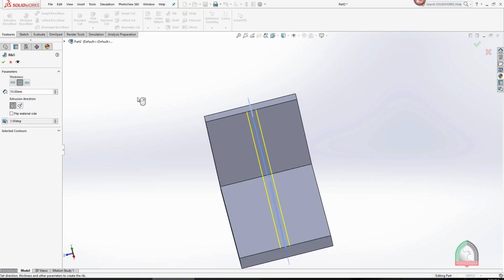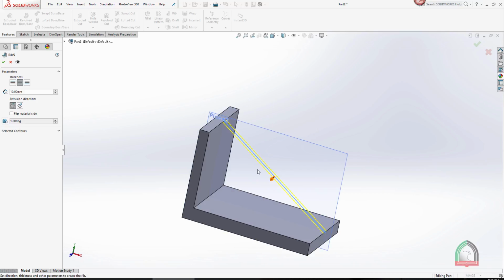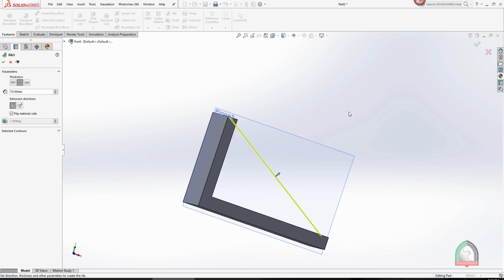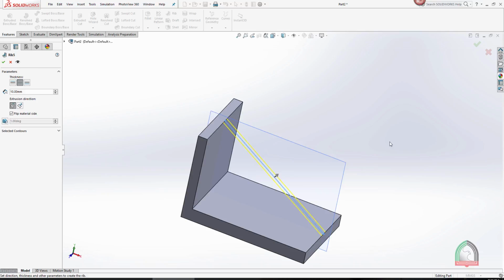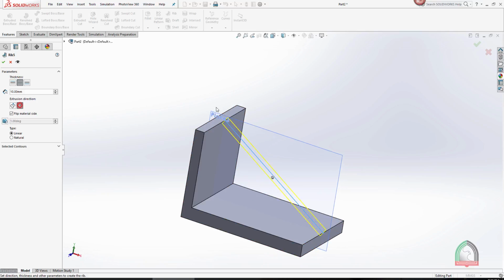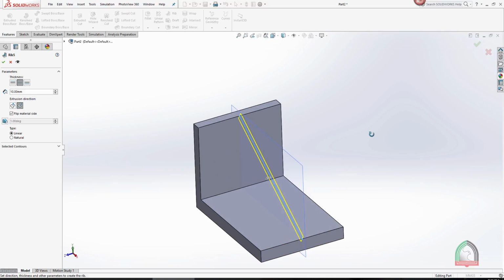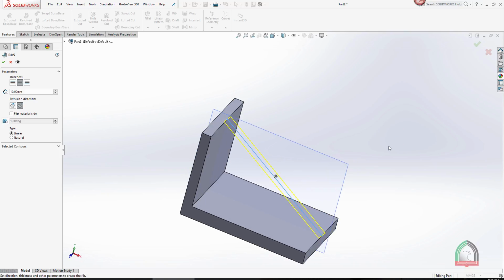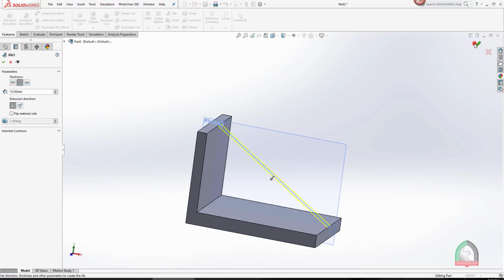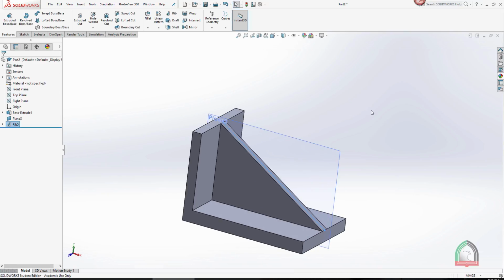And there is one other option. Here you can see that the rib will be completed by using material only. If you are reversing the rib, we cannot complete the rib because there is no constraint over this side. And there is one more option I will show you. This also will not work because the rib will go and finish in a particular face. There is no face in this direction, also in this direction. So the only option is to go down. So this is the option. Once I click this, you can see that it's completed.